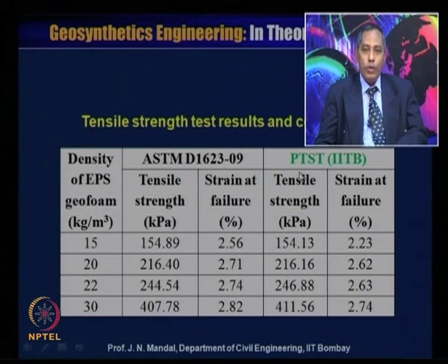Whereas in the proposed method at IIT Bombay, the tensile strength is 154.13 and strain at failure 2.23. You can see that a lot of similarity is there between the ASTM and the proposed tensile strength method, and this test is recommended for use in India.